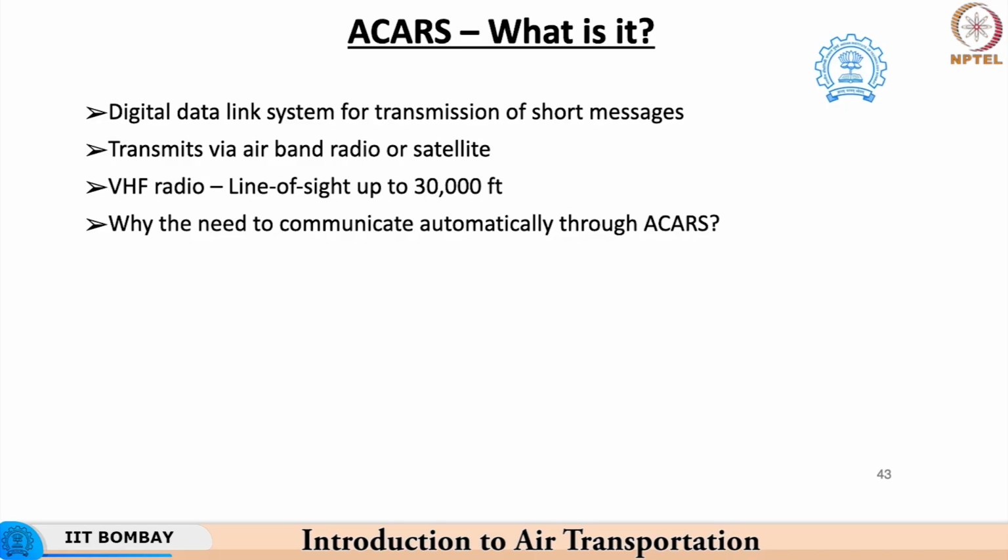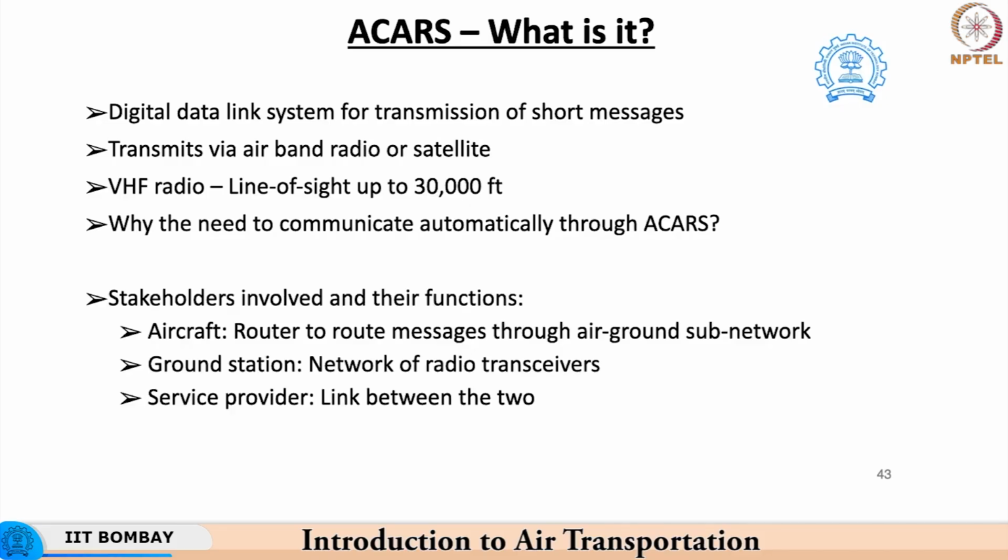Moreover, there has been an increase in air traffic nearby the particular aircraft, because of which there has been an increased workload on the pilot as well as the ATC. Hence, there was a need to carry out communications in a more automatic manner, thereby the need to implement ACARS. So the stakeholders involved in this type of communication is the aircraft, which makes use of a router to carry out the overall transmission through the air ground subnetwork.